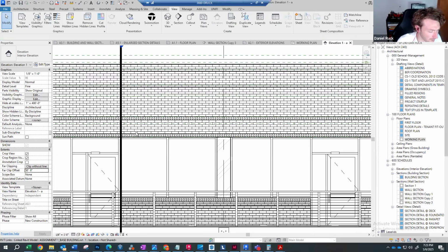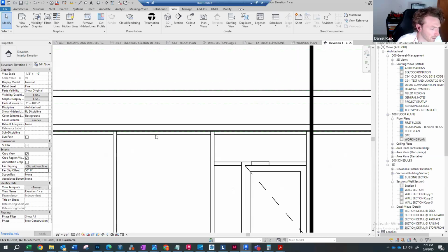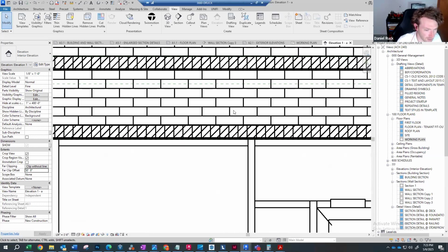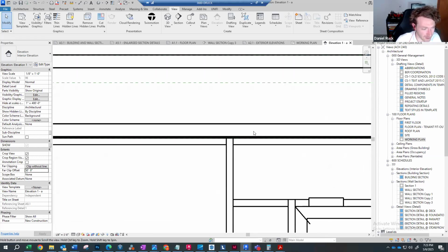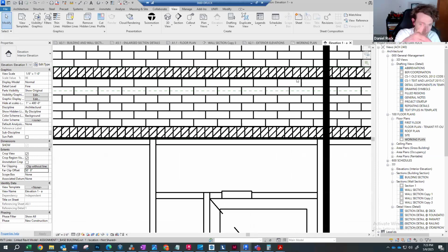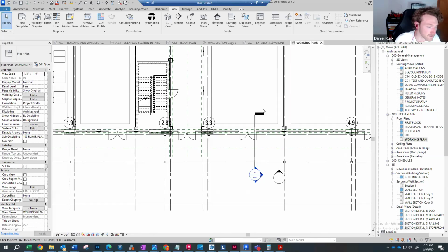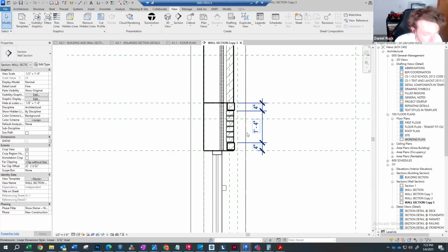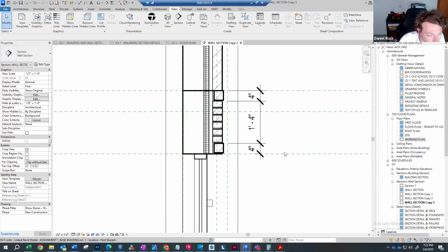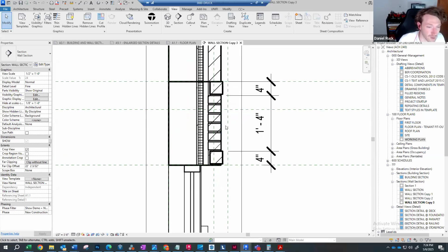When I'm looking at the coursing, you can see we have our regular modular brick, but then we have a row of coursing here and a row of coursing here that is flipped on its side. This is 4 inches and 4 inches. Again, the rule of thumb when you're working with brick and masonry is we always want to be within a 4-inch or 8-inch coursing. If you're not, it's most likely due to incorrect masonry coursing heights.